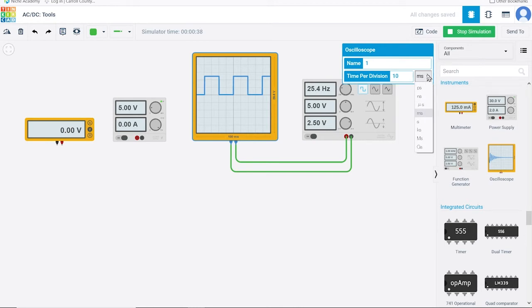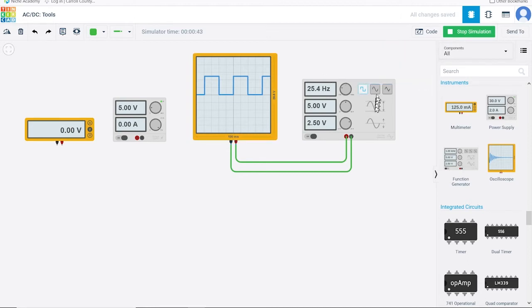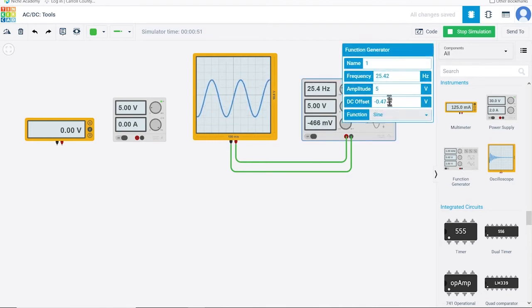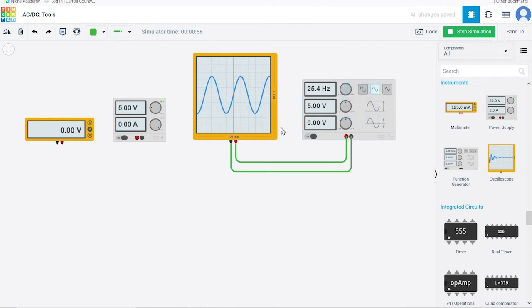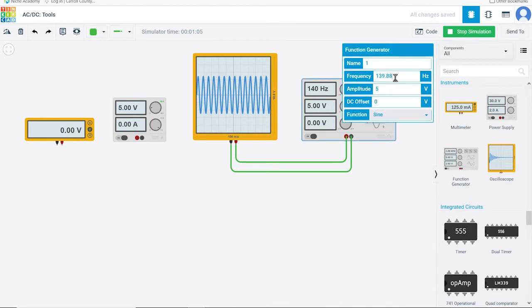The electricity that comes into our homes is 120 volts at 60 hertz. In other words, 60 times per second, the voltage changes from positive to negative and the direction of current is reversed. We won't worry about AC too much in Arduino projects or even most hobby projects. It's all DC. By convention, the positive terminal is denoted by red and the ground terminal is black. This color convention is used throughout electronics, so keep in mind that red will generally signify the positive side of a battery or power supply, and black will signify the ground terminal.